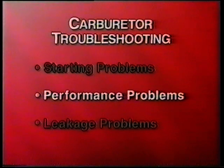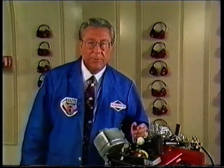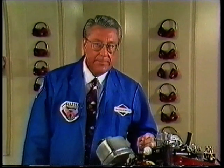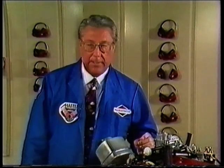Performance is another category of carburation problems, and they come in many varieties. Maybe the engine won't idle, or idles poorly, or it may run poorly at top no-load speeds, or under load, or there may be a combination of these symptoms. The problem is most commonly described as hunting and surging.